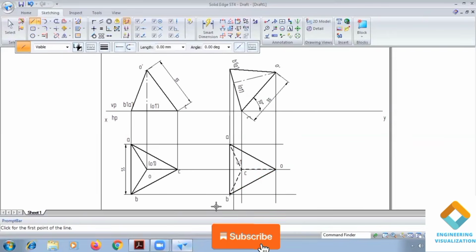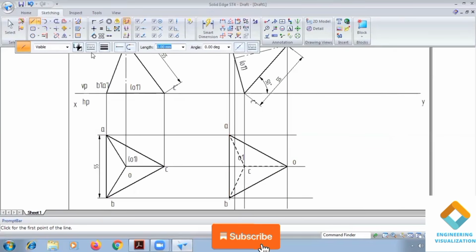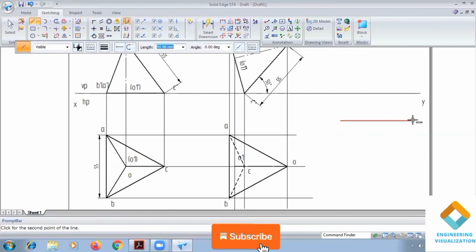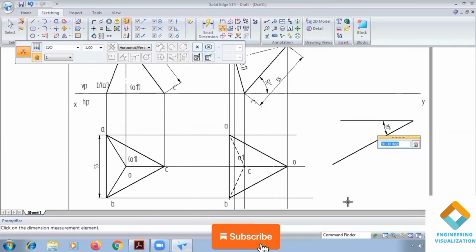Now we need to find out the beta angle here. So mention the axis. Here in this problem they have given the angle of inclination with the edges, but the concept of the beta angle is that it is with respect to the axis, but this is one of the special types of problem. Here the angle of inclination is given with respect to the edges for both the HP and VP planes. That's why it is also a beta angle problem. Angle 30 degrees. So if you give minus 150, it will take 30 degrees.